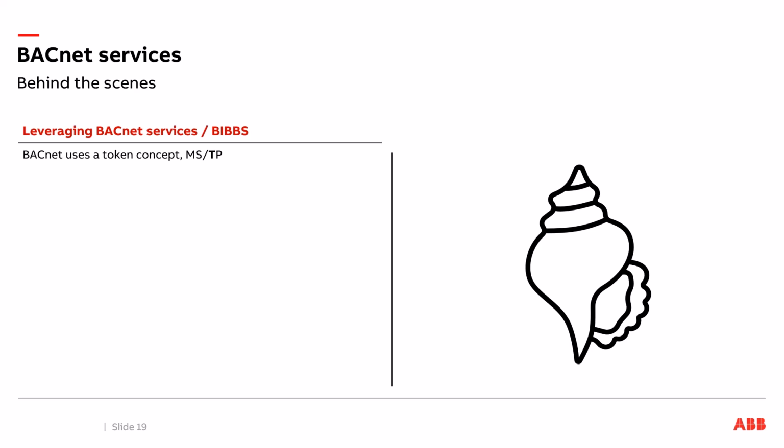So that's essentially what the token is within BACnet MSTP. It's a conch that's going around the BACnet wire. And when you have the token, you've got the conch, you are allowed to talk. So that's how they keep these wires from crashing, is everybody has their turn to talk. So that's what MSTP is, master slave token passing. You can always consider the token to be the conch if you ever read the Lord of the Flies book.